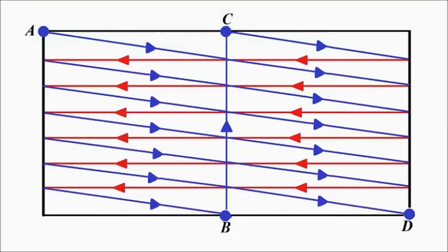So here the scanning takes place in this way. It starts from the extreme left at the top, from A here. It moves from here to here. Again the retrace, the red portion, the red arrowhead. Again it moves from here to here. Retrace, scan, retrace until it reaches B. So one half portion of the frame is scanned.